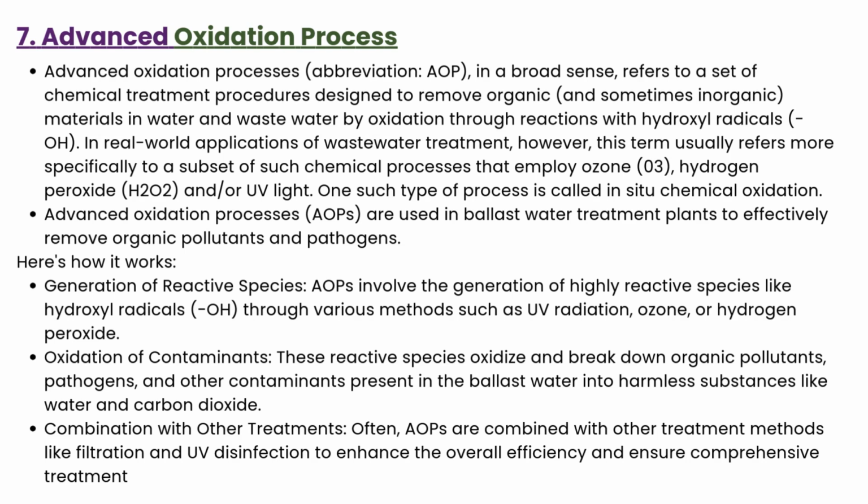Oxidation of contaminants: these reactive species oxidize and break down organic pollutants, pathogens and other contaminants present in the ballast water into harmless substances like water and carbon dioxide. Combination with other treatment: often AOPs are combined with treatment methods like filtration and UV disinfection to enhance overall efficiency and ensure comprehensive treatment.